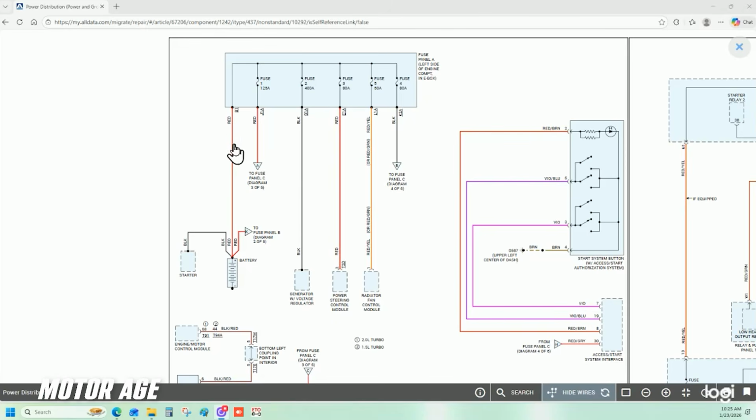When the problem is present on the first channel, what we call channel A, what you will see in blue, in channel B, we are trying to answer the question, where is the problem? Which path does the problem reside in? So channel A tells us there's a problem, and channel B is going to tell us, is the problem in this circuit, yes or no? In this circuit, yes or no? This one, and this one, and this one. And whichever circuit houses the fault, that is the circuit we are going to pursue.